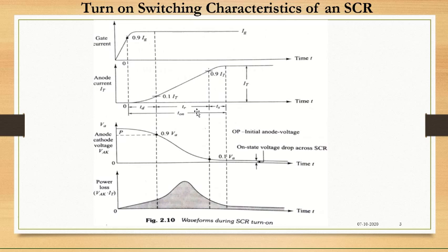So the rise time is nothing but where our anode current increases from 10% of its final value to 90% of its final value. See, when you are explaining, it is not only that you say the device is turning on and the current is increasing, but in the background you should know its structure, its internal operation, eventually the basic electronics.